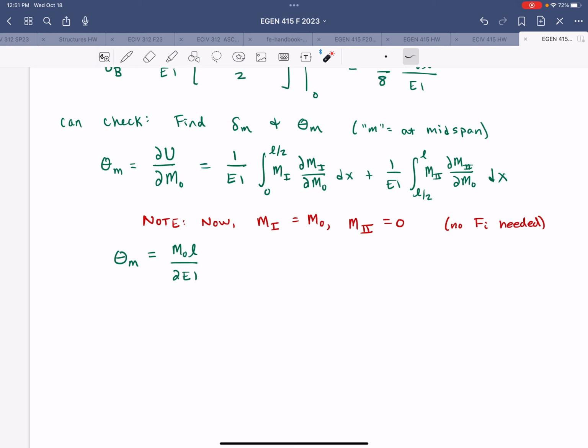Okay, so no, because it's bending, right? So you need the bending stress equation, yes. Because you're saying for that force over area, you're taking the Q? That would be the normal force in the Y direction, which we're neglecting in this case.